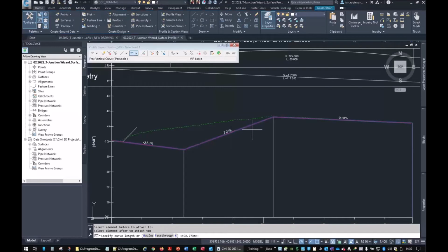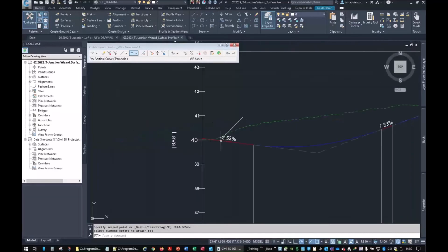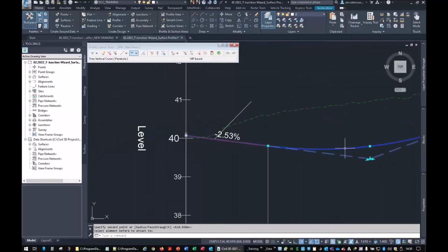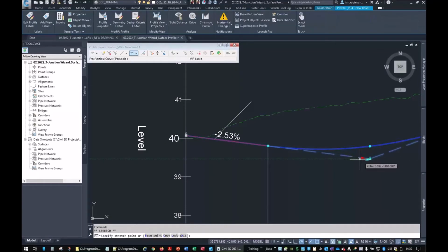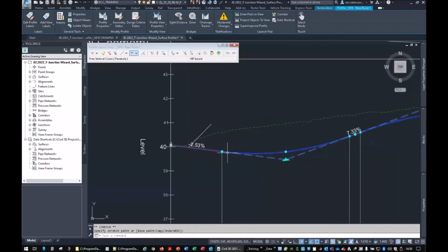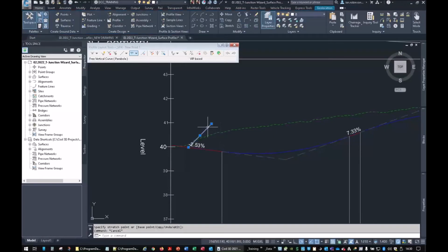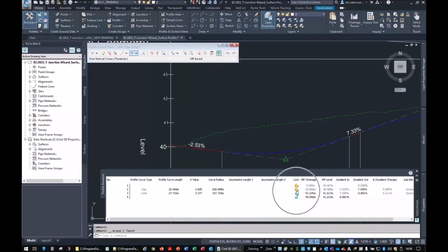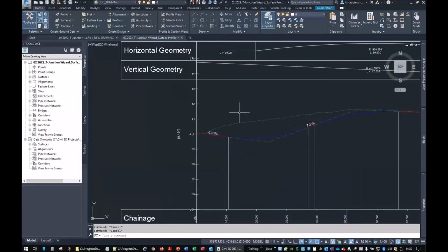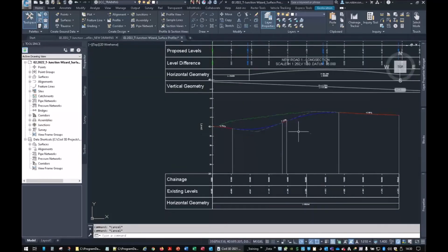So I'll now put my vertical curves in, there to there. And we'll just draw something in, making sure we don't interfere with where the existing carriageway is. Okay, so I can move that over if I want to, but as long as I don't go beyond that line, I won't interfere with the existing carriageway, essentially. So I'm happy with that. I can delete that line now. I can go into here and relock that point. Okay, all nice and locked.